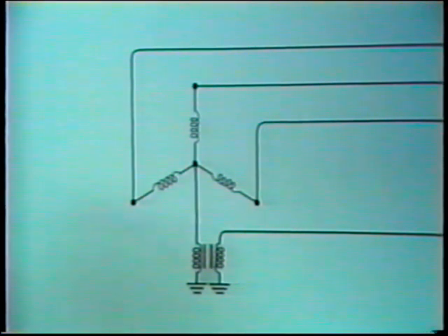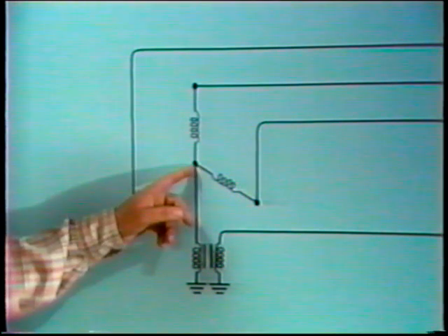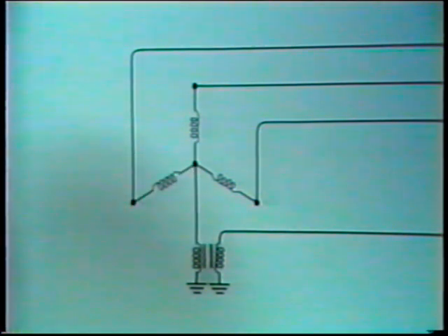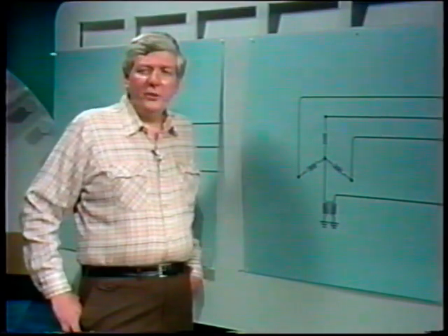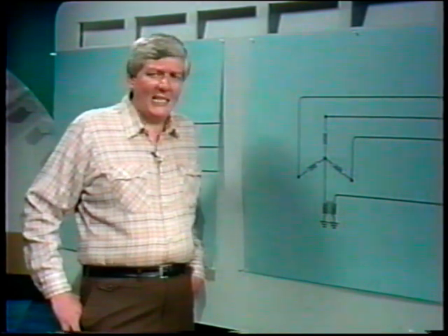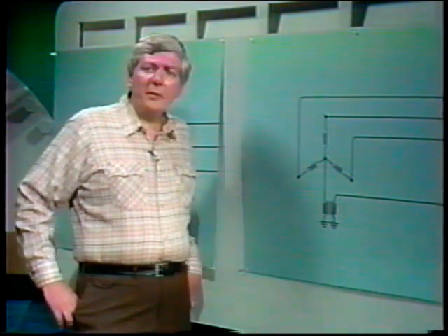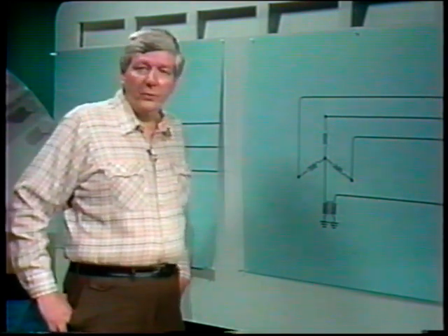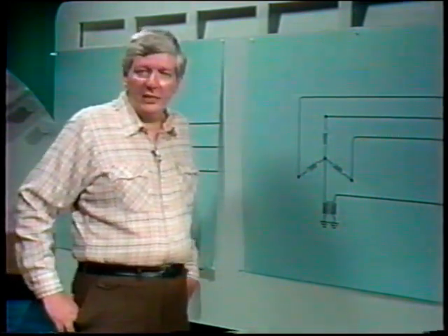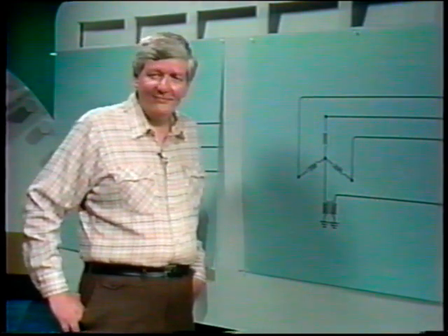As you can see, one end of each winding is connected to a common point. With this arrangement, voltage is higher for a given power level than in a delta-connected generator. An important feature of Y-connected AC generators is that they can be connected to ground conveniently. As a safety measure, their common point of connection, or neutral point, is connected to ground. This helps to detect grounds elsewhere in the generator.